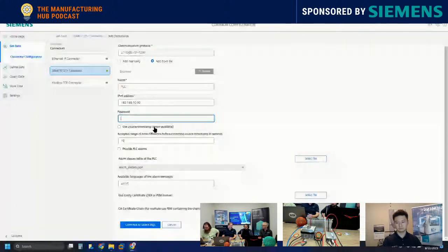And a lot of what goes on when you're trying to do analysis of data is you're trying to line up events from disparate systems. So getting things to be in time is really important. If you're using a PLC that has the time source availability, use it. If you don't, the edge device can apply its time, and it's going to be very close because of the short distance in time from when you're reading the data to when you're archiving it.